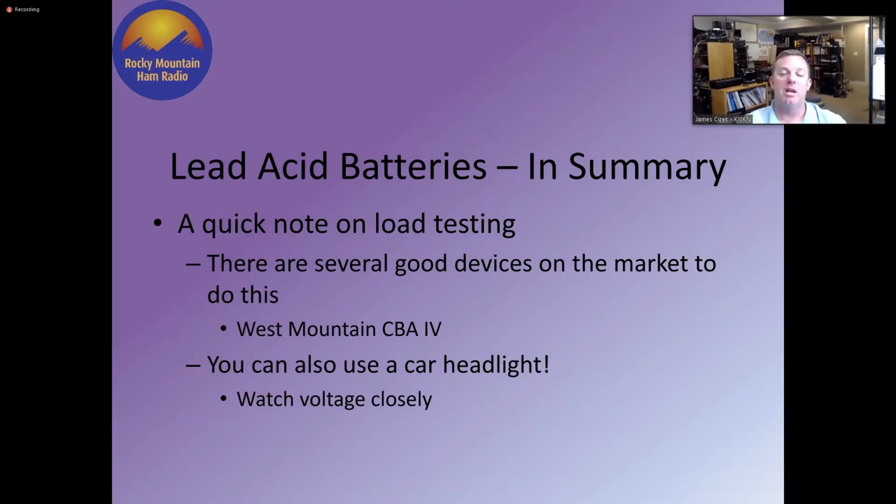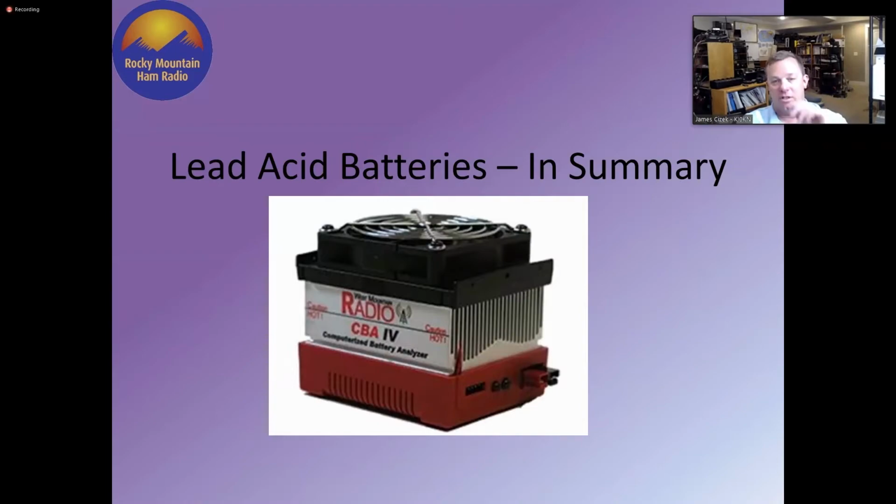The West Mountain computer battery analyzer is a really neat little way to do it. If you don't want to spend that money, you can use a car headlight as a discharge device. Just watch your voltage real close so you don't discharge too far. That's what the little CBA4 looks like. You plug a battery in and it hooks to the USB of your computer and it plots a real chart of the whole discharge for you.